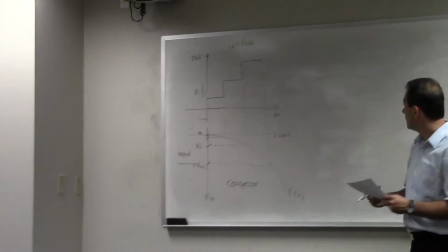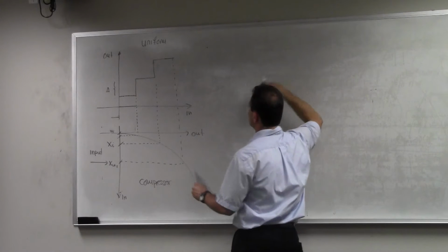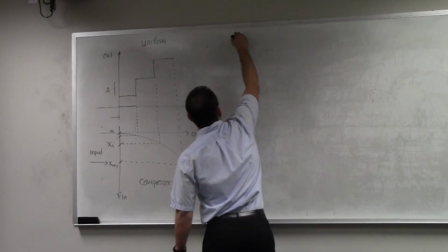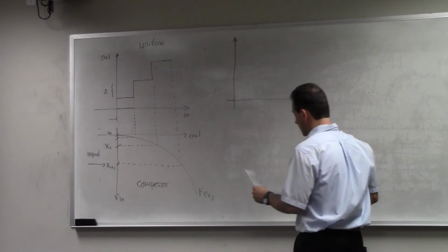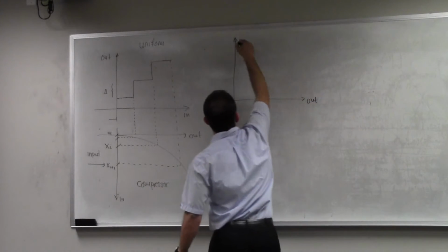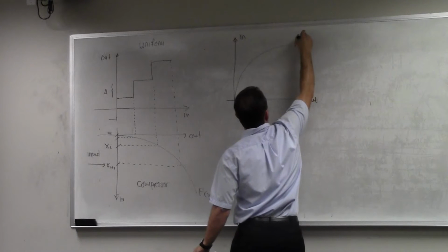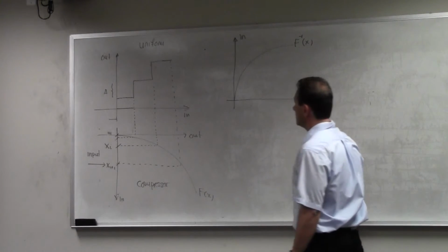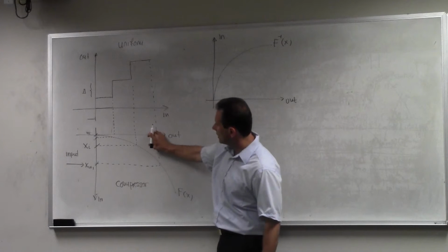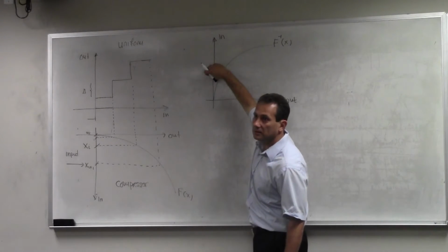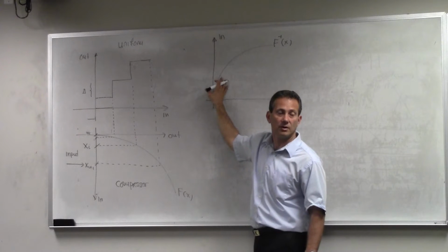Now, once you go through quantization and feed this into a communication system and recover your quantized signal levels, you have to actually do inverse mapping. So this is the output, and this is the input for this one, and you're going to have a curve that is an inverse, I'm going to say f minus 1 of x, of this curve here. Just to see that it's an inverse, look at this one is close to the out, and this one is close to the in, right? So the net product of these two is going to be equal to 1. They're going to cancel each other.